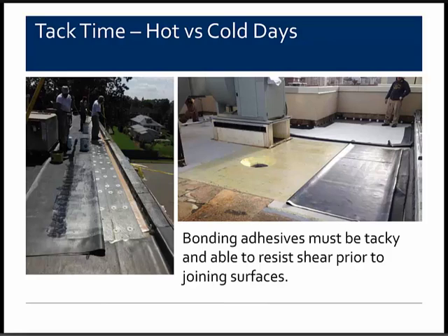For some solvent-based adhesives, after the application of the adhesives to the two substrates being bonded, the solvents in the adhesive need to flash off or evaporate prior to mating the two materials. This flash-off period would vary greatly with the temperatures. Hot days, it typically flashes off relatively quickly within the first few minutes, whereas on colder days, that flash-off period is actually a little bit longer.